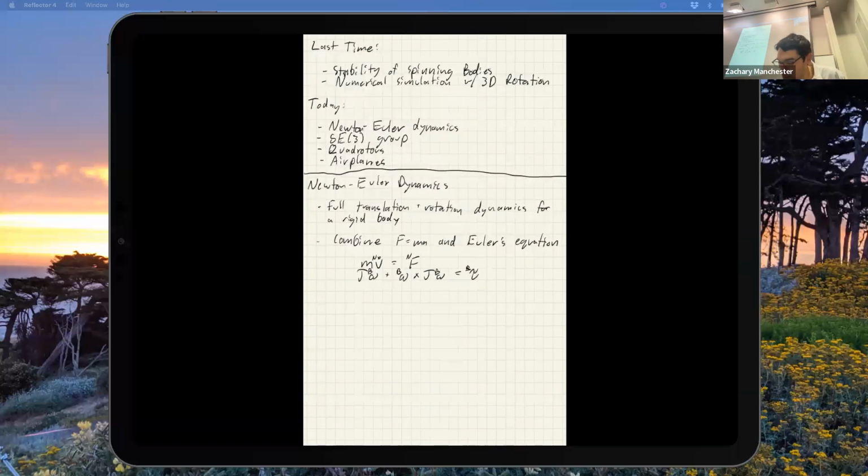So you will see both of these. And I think I made this typo in J omega dot. Yes, J omega dot. There's a dot on this guy. Thank you. I hopefully made the point in the rotation stuff that there are a million different conventions for writing down rotations. You can write down the attitude as body to inertial or inertial to body, and you could stack the quaternion up in different ways and all this stuff, right? Generally, the convention in aerospace and robotics is body to inertial, but that gets violated all the time. You'll see books where they do it the other way.